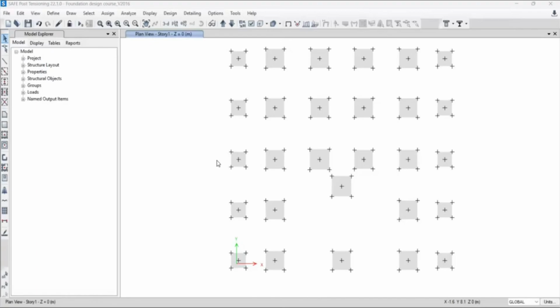And if your footing is settling less, then it is fine. But if it is settling more than 25 millimeter, then you probably need to increase the footing area, so that the foundation has enough area to distribute the load on the soil. So let's check this.